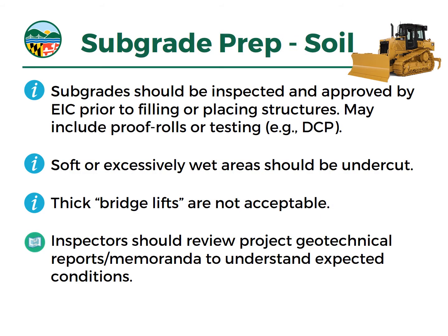Okay, on to subgrade preparation and soil foundations. We want to stress that the subgrades should be inspected and approved by the engineer prior to filling or placing structures. Sometimes that may mean including proof rolls or testing as well.